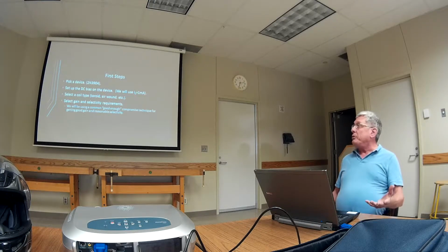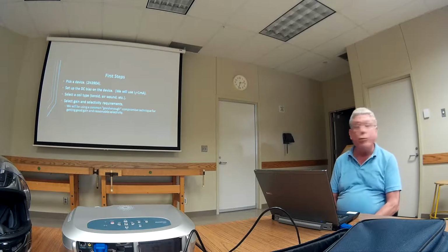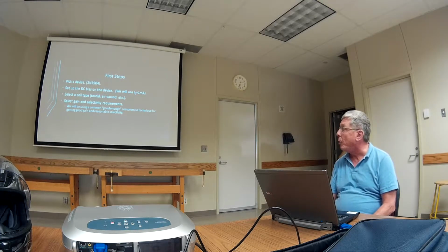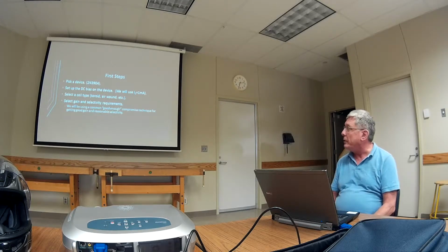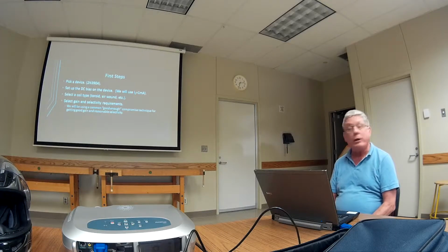We've got to pick a device. I don't know, 3904, 2222, any of these will work. Got to have some DC bias. These are going to be Class A small signal amps. I just picked a milliamp. That's what I usually do when I'm doing these experiments.